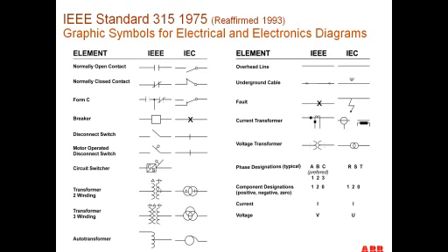For us, we have a series of windings back to back. In the IEC world, they just use two conjoined concentric circles. A three-winding transformer, we use three sets of windings to show you that. And in the IEC world, they just use three symbols joined together. So sometimes it's easier to use the IEC symbology if you can. And then, of course, going over to the phase designations.